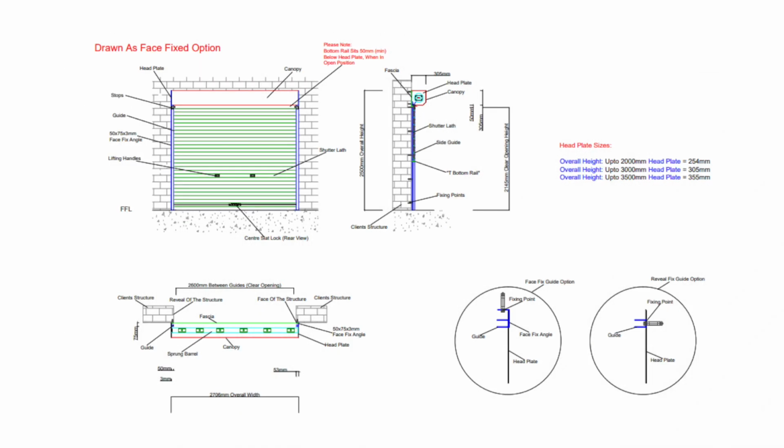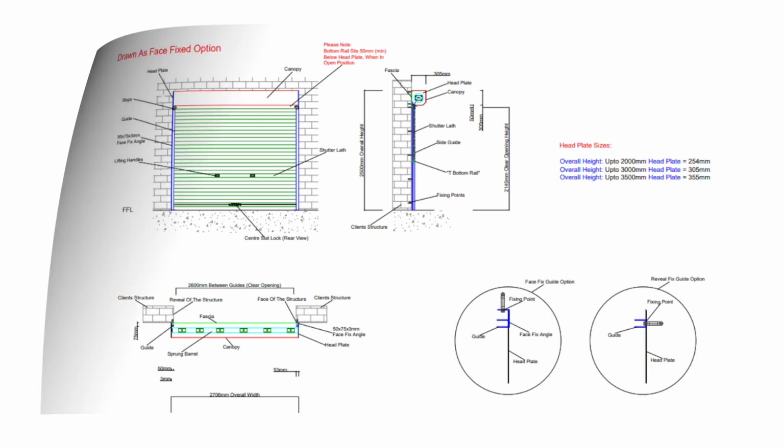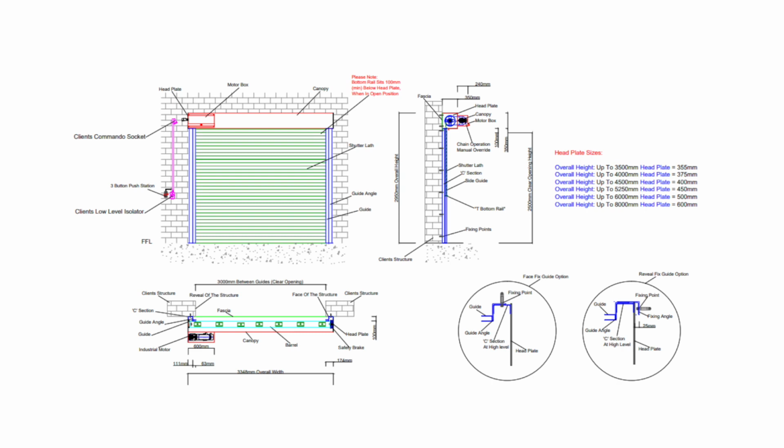For manual operation, a counterbalanced helical spring, managed by a hand chain with a chain lock, controls the industrial shutter, and a double spring unit in the barrel assembly acts as a chain-operated anti-fall device to prevent closure in case of a single spring failure. Electric operation uses a standard push-button control with customizable controls, and additional safety devices can be added as needed for specific requirements and operational conditions.